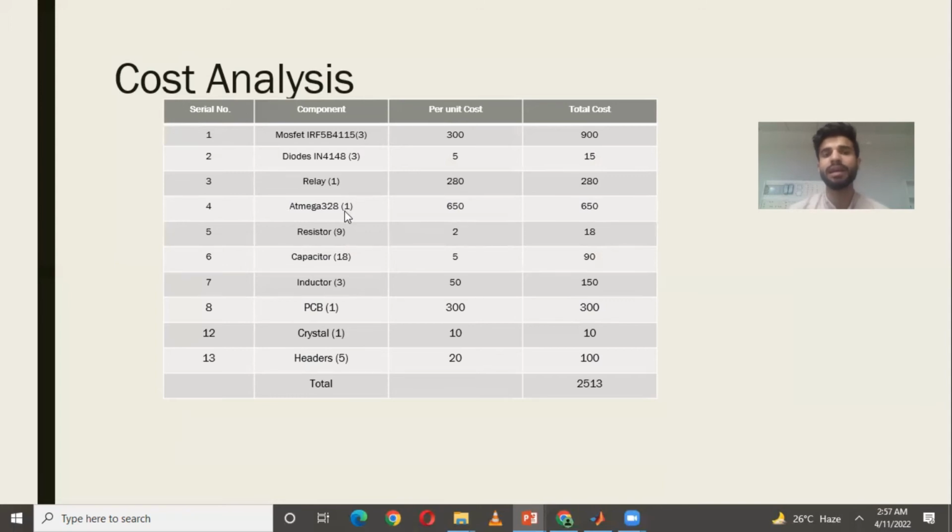We have used ATmega 328P for sensing the input as well as producing three different duty cycles for the buck boost circuitries and a digital signal for actuating the relay. The relay also needs VCC of 5 volts and ground, which we have given from ATmega 328P pins. We used resistors as loads of different values. We also used capacitors according to the mathematical modeling, and also the inductors.